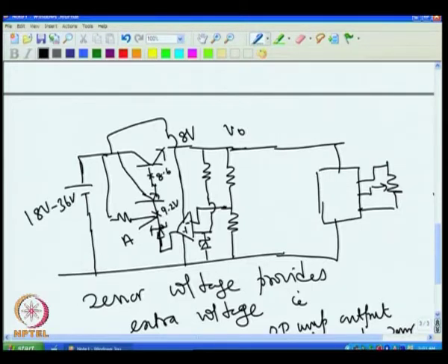But if you do this, when the supply voltage changes here, the current consumed by the whole circuit should not change. The current flowing in this line should only vary because of this. So, that is why we are not connecting the supply for the op amp here. We connect the regulated output, because the regulated voltage is always constant irrespective of what is at the input. So, the current consumed by the op amp will also be constant. That is why we connect it here instead of there.